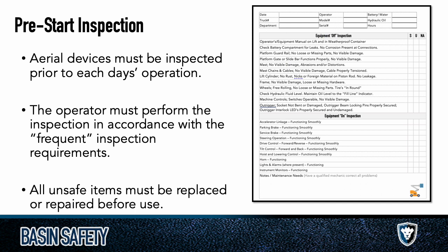As I mentioned, you're going to do your pre-start inspection. It goes through the list again. Hydraulics, is the alarm working? Does it reach its maximum potential? There's an on-the-ground inspection on our form. Not all of them have this, but we have an on-the-ground one, and then once you turn it on, you have another set of checks that you do.